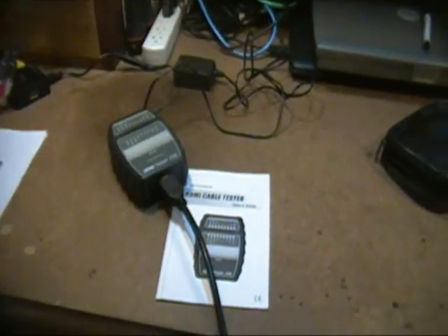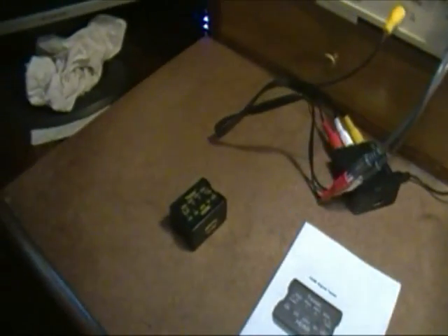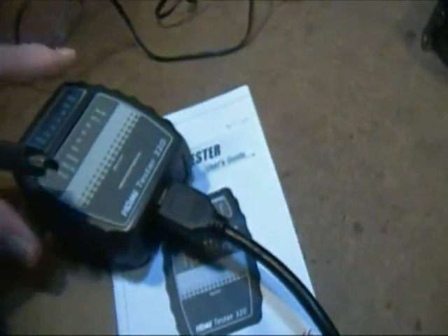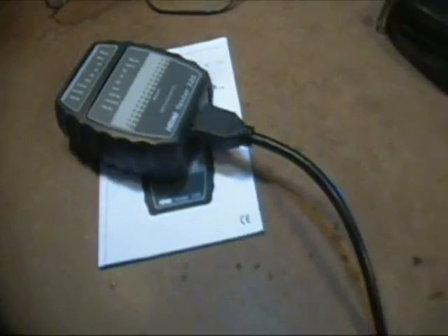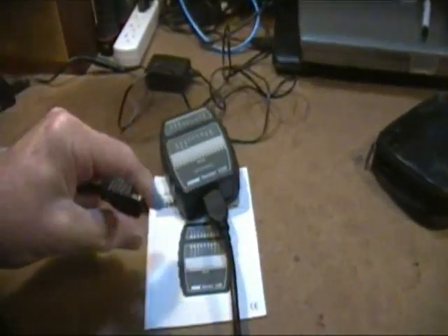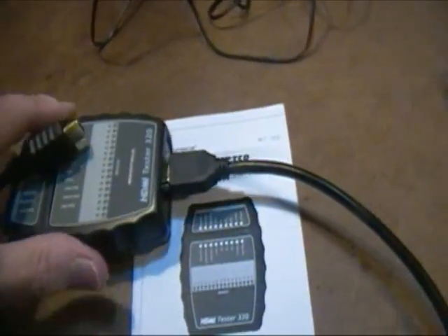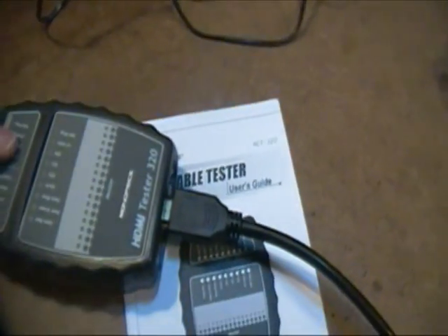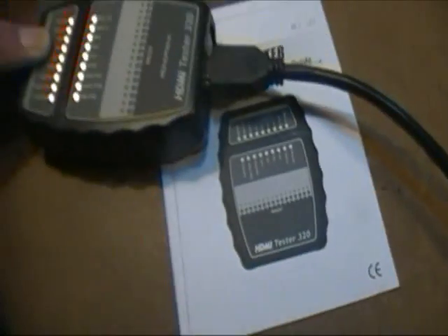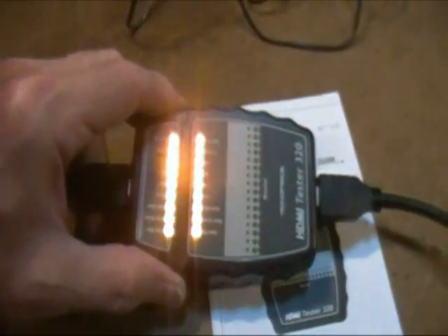So let's do that, and then let's talk about what you can and can't do with these testers. This is the cable that I was using a little bit ago to work on that signal tester over there, and let me emphasize again, signal tester you can use on the signals, a powered up device. The cable tester is not connected to a powered up device. In fact, let me show you that this is just a cable going from one side to the other. It's not connected to any sources of power except the tester itself. So let's plug it in. And you notice that all the lights came on.